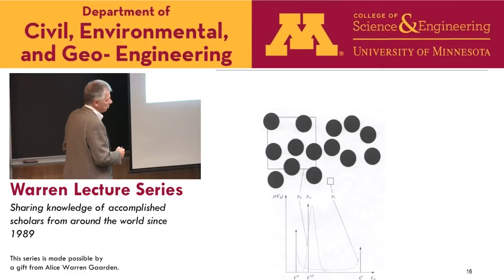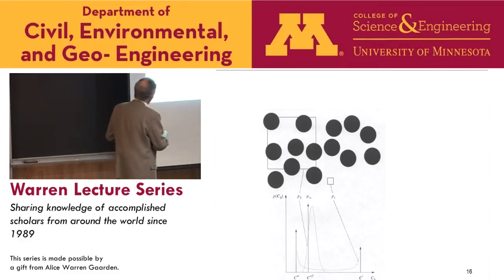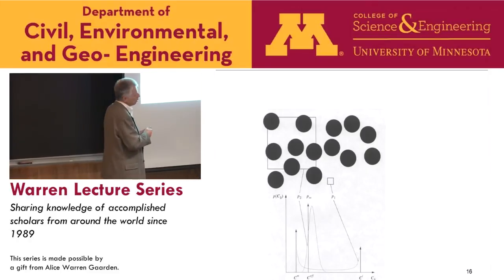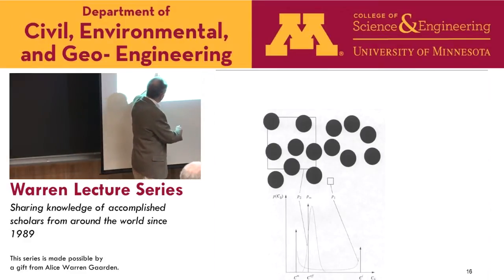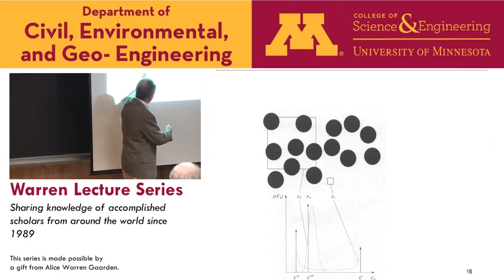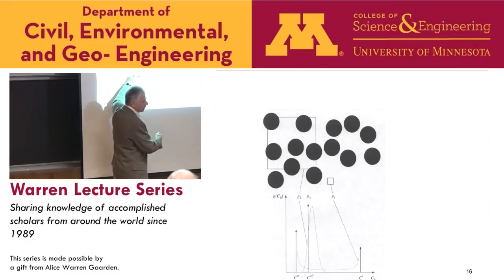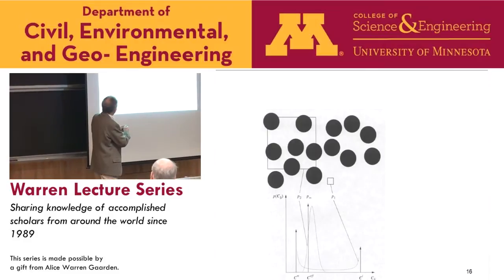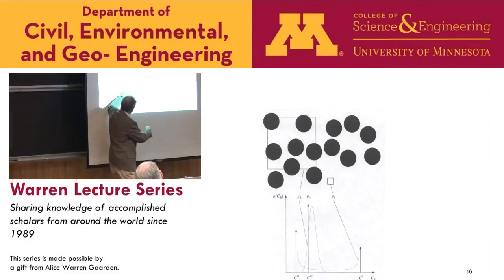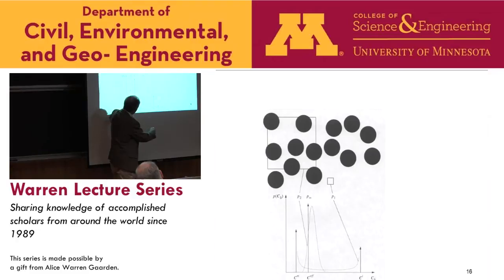And one can also talk about the behavior of statistics, say the probability density of properties. If I sample with a pointwise window, then I either hit the black or white phase. There's 0 probability of hitting the interface, which is an undefined property. So then I have 2 Dirac deltas for inclusions in a matrix whose strength corresponds to volume fractions, right? But if I sample with a window which is somewhat bigger than a mathematical point, then there's some chance that I will sometimes hit the interface. So then I'm looking at a probability density, which is bounded by these 2 Dirac deltas.